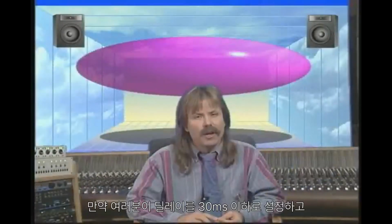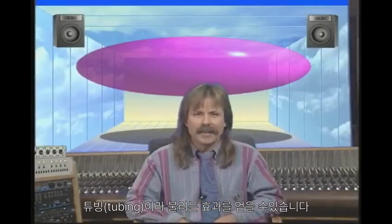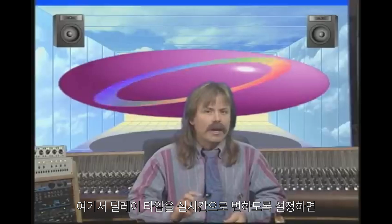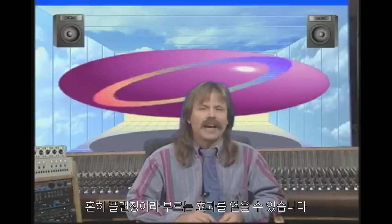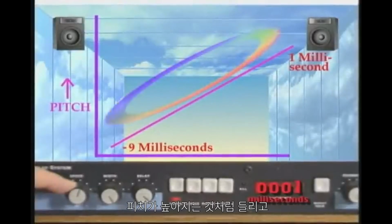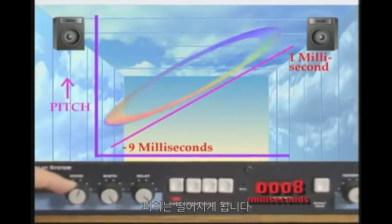If you set the delay time for less than 30 milliseconds and crank up the feedback, you get an effect called tubing. Totally tubular. If you then change the delay time, you get an effect that sounds like this. If we set a clock to change the delay time on its own, we get the effect commonly called flanging. Notice that as the delay time gets shorter, the pitch seems to rise. As the delay time gets longer, the pitch seems to fall.